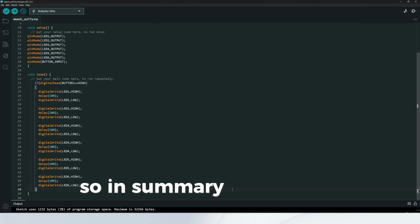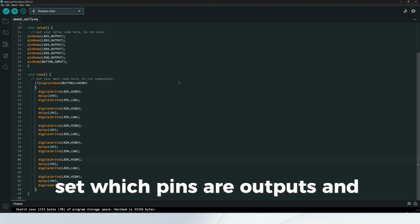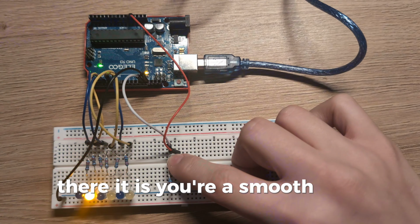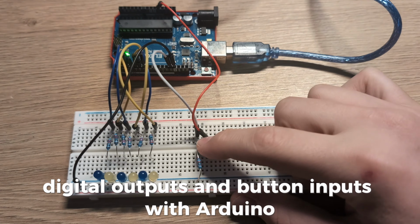So in summary, at the very beginning, define the pins for LEDs and the button. In the setup, set which pins are outputs and which are inputs. In the loop, check if the button is pressed. If it is, make the LEDs light up one after another. There it is, your smooth LED wave effect. This is a great beginner project to learn about timing, digital outputs, and button inputs with Arduino.